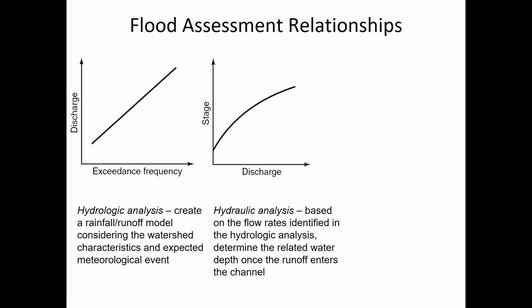The next way that you understand how to change the risk of damage is by doing a hydraulic analysis that says, for a certain flow rate Q, how deep is the water going to be in the channel? Whereas you'd use WMS and set up a hydrologic model like HEC-1 or TR-55 or maybe National Stream Flow Statistics, that's how you'd come up with this curve. For the hydraulic analysis curve, you'd use HEC-RAS. HEC-RAS is a program where you build the geometry of a channel. You're telling it how wide the river is, the side slopes. You're telling HEC-RAS the Manning's n value, the roughness associated with the materials there. And then you send a certain flow rate through the stream, and it'll tell you what is the depth for that flow rate. So here we have, at a variety of increasing flow rates, how deep the water is going to be.